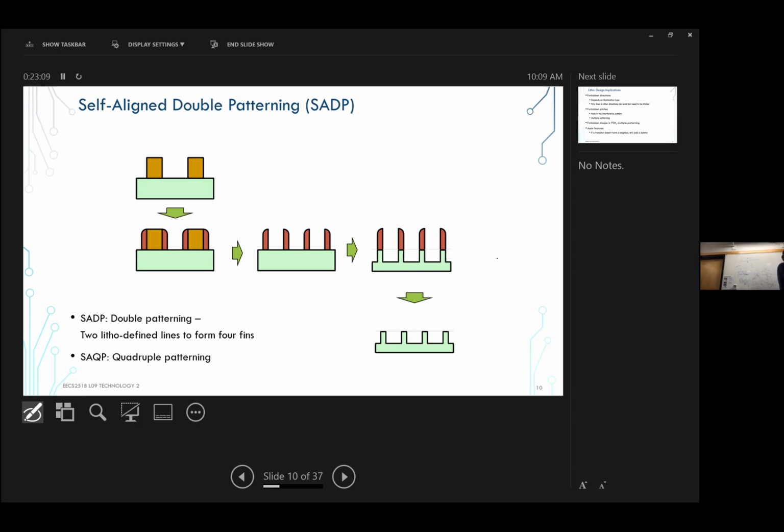Nothing. You just turn them off. But there are things, if you're doing some precision analog stuff, this will cause you trouble. Even in digital, there are leakage paths associated with these off transistors. If the well on the other side is biased to something else, this thing will tend to leak, and it causes a lot of headaches.